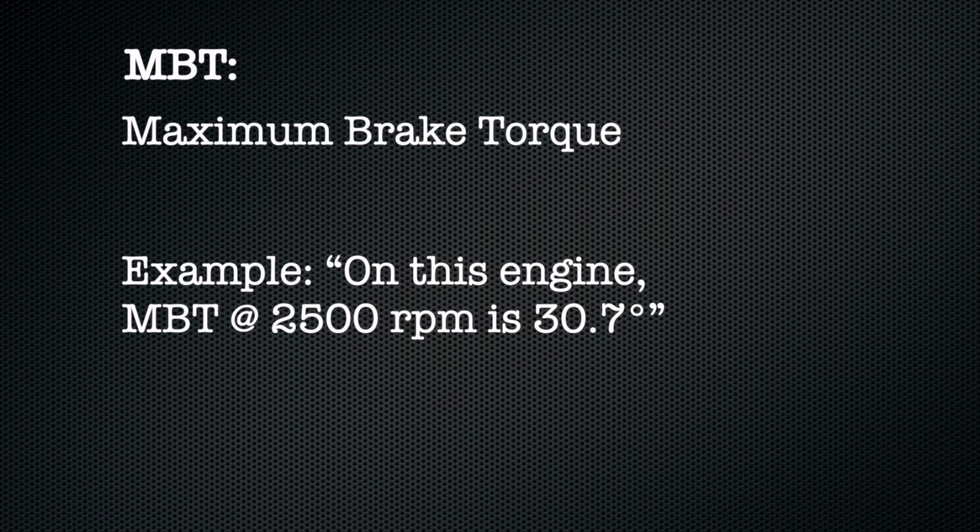Just as a side note, the degree timing that produces the most torque is called MBT timing. MBT stands for maximum brake torque. It's called brake torque because all this stuff is typically measured on a dyno, which applies a brake to the engine to produce load. So the torque that the engine puts on the dyno is called brake torque. All right, now you can impress the hot rod guys with your trivia knowledge.